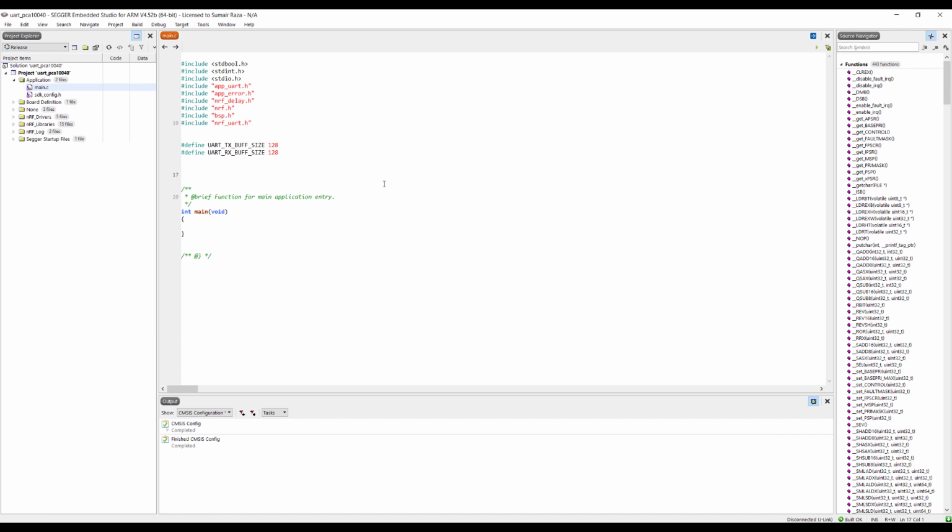Okay, so the next thing is we have to create a constant for hardware flow control. Basically we don't use the hardware flow control unless we are using very high baud rates, so we will disable that. To do that, we have to define a simple constant.